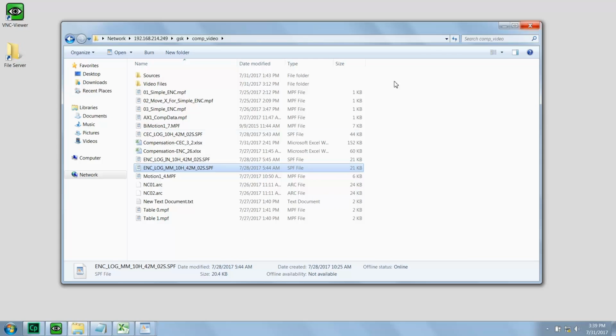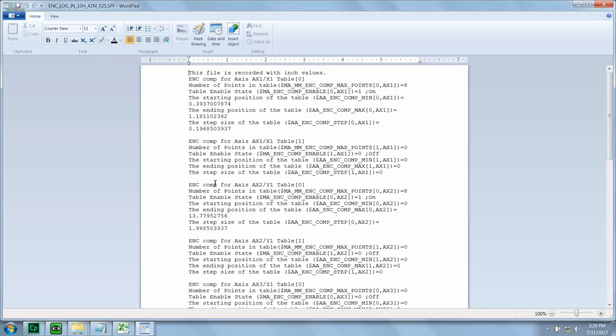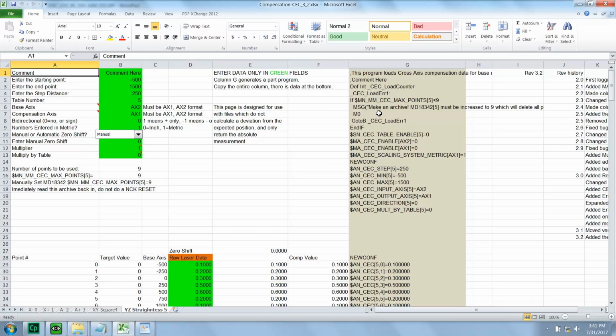If we look at the inch file, we will see that we have values in inch, except now instead of being a round number like 10 millimeter, well, it's still 10 millimeter, that's just not very round in inch. So we get both data, so depending on which way the machine was configured, you can get good round numbers in either.